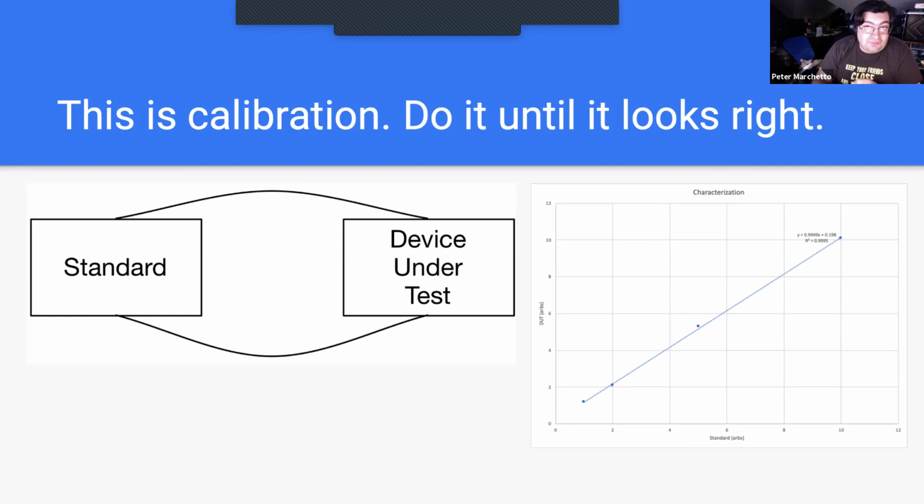And we've actually run into that too, where one area of our graph will look great, and then the rest of it might be just not so good. It'll be a lot more noisy, and that will be the area that we need to improve, generally speaking. That's also something that we see with probes that aren't exactly performing to our spec. They might perform great in a very limited area of the calibration or the characterization that we're doing, but then the probes might not perform well at all at a lower value or at a higher value. And so because we've got a high density of data points in that area where they perform well, the R-squared value is going to look great, but the actual performance sucks.